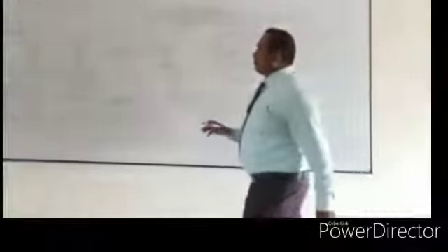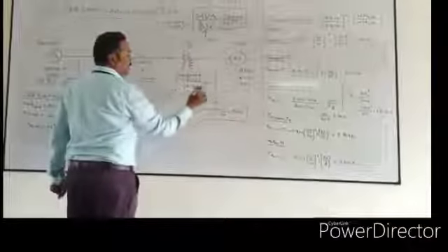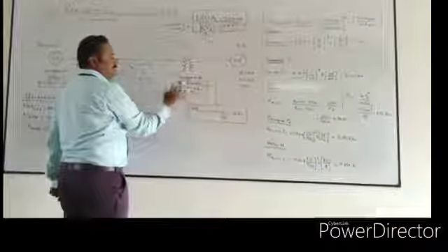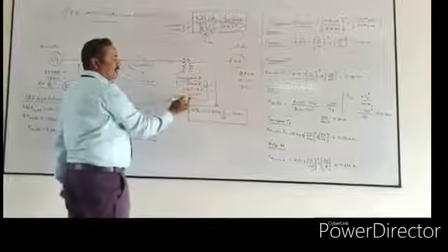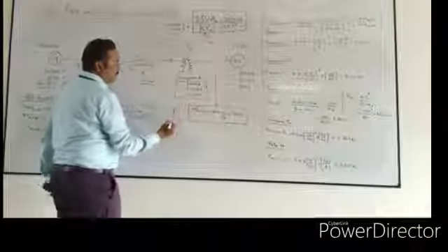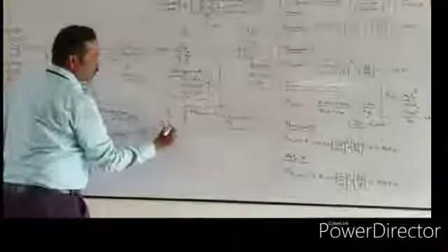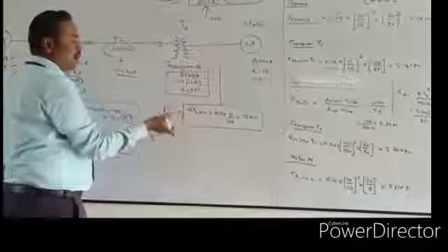Now we come to the primary side of the transformer T2. So now again you can see that the old base values are given in the nameplate: 20 MVA. So this is going to be a step down transformer, 110 kV by 11 kV, and the reactance value is 20%, and this can be written in per unit as 0.20. So this is the old per unit value. Now we are going to see what is the new per unit value.